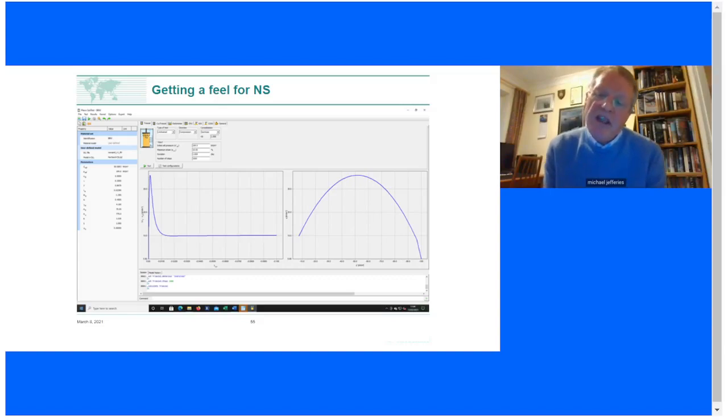And there's a serious point here, because as an engineer of record, you should not be producing a judgment saying, aha, I have this reference and Mike says this, and because Mike said that, here's the reference to Mike saying this, ergo, this is what I'm using. No, no, no, no. You must follow the Russian proverb as an engineer of record: trust is wonderful, distrust is better. What you must do is ask how well this framework works for the soil I'm engineering. Check for yourself that it actually fits your test data. Check it fits your stress-strain curves.